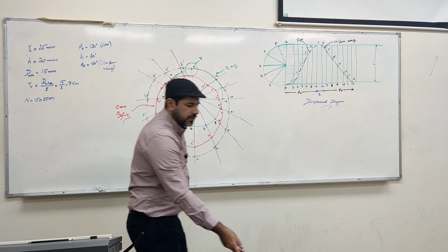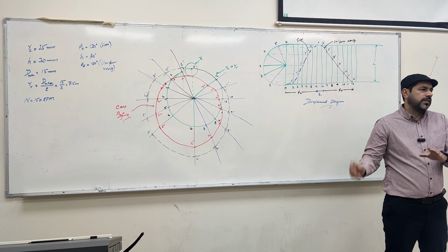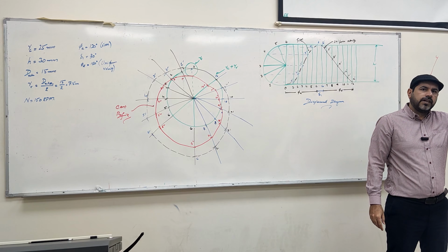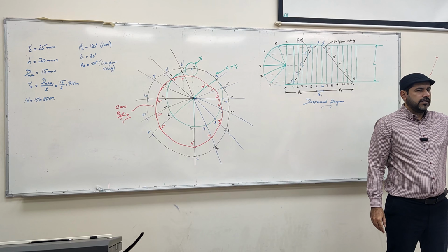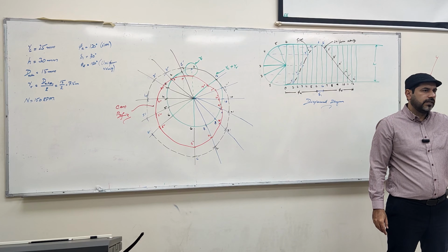So what is the difference between case 1 and this one? Case 2 is totally different because it was offset. In case 1, we have a knife edge follower, which means it's basically point contact on the surface of the cam profile. This one is a roller.